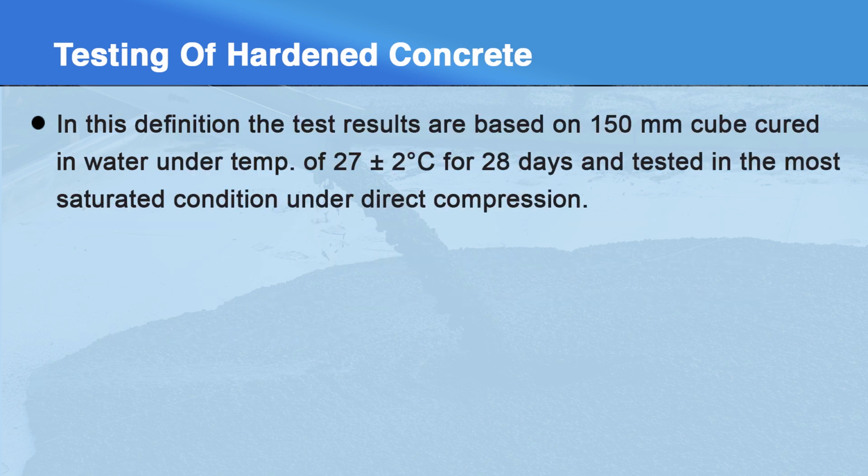In this definition, the test results are based on a cube of 150 mm size, cured in water at a temperature of 27 plus or minus 2 degrees centigrade for 28 days, and tested in the most saturated condition under direct compression.